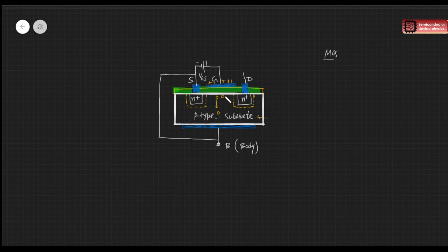from this interface. So you can see that this region will become less p-type as we keep increasing this VGS, and if you keep increasing the VGS amount, after some time the inversion happens, right? So this region of the semiconductor will slowly become n-type. Here there will be all negative charges, or the electrons. So at that condition, if you draw this diagram,